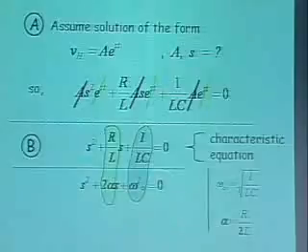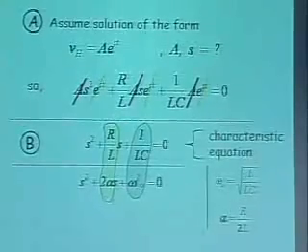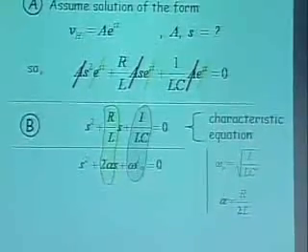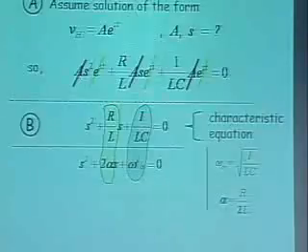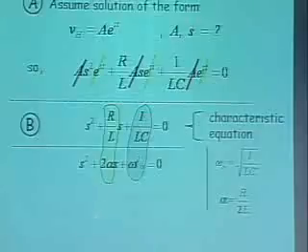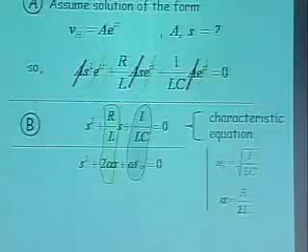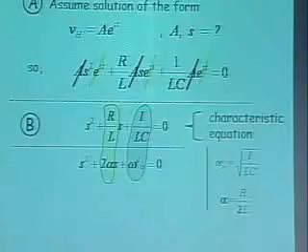Once I get to this characteristic equation, after that, I can give you one generic way of solving it, and depending on the kind of circuit you have, a series RLC, which is what we have, or a parallel RLC, you will simply get different coefficients for the alpha term. This is going to stay the same, but this term will look different. Alpha is going to look different. There's a real pattern here. What I'm doing is simply focusing on what's important, what the differences are between the pattern you've learned in the LC situation and the RLC situation.